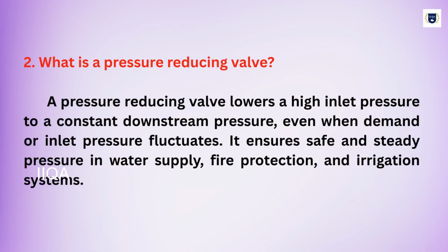What is a pressure reducing valve? A pressure reducing valve lowers a high inlet pressure to a constant downstream pressure even when demand or inlet pressure fluctuates. It ensures safe and steady pressure in water supply, fire protection, and irrigation systems.